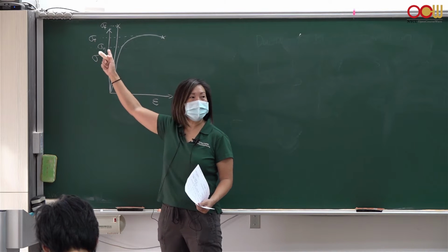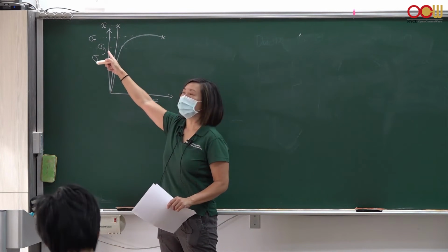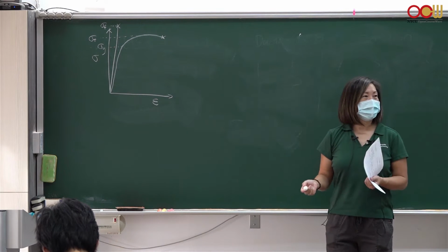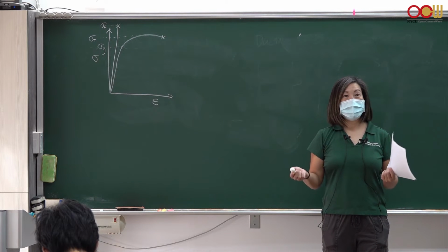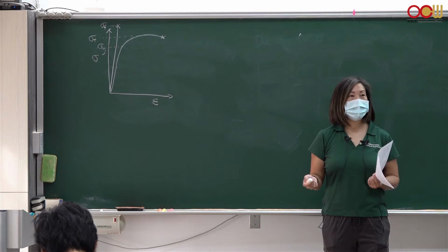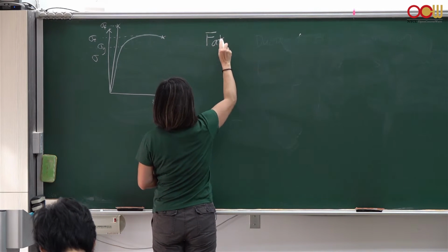So a couple of other scenarios where your material will break below the fracture stress or the tensile stress, or maybe will start to yield, so permanently deform below the yield stress. We need to know those things because, if you calculate a yield stress for a material and it starts to yield below that, then you need to consider that into your engineering design. The first one, it's called fatigue.